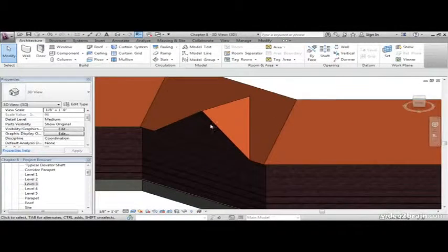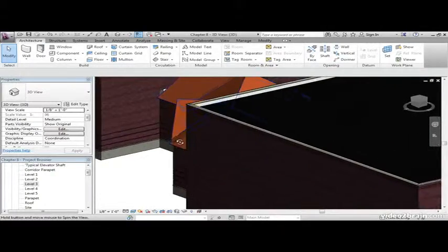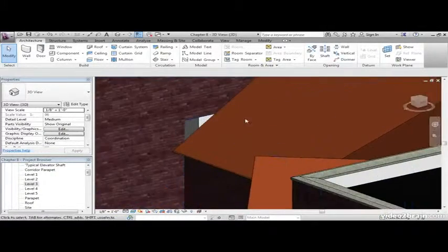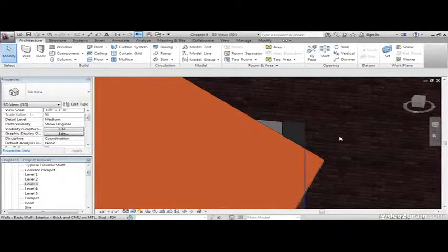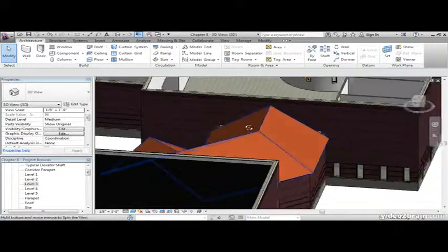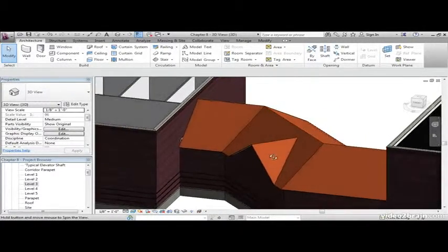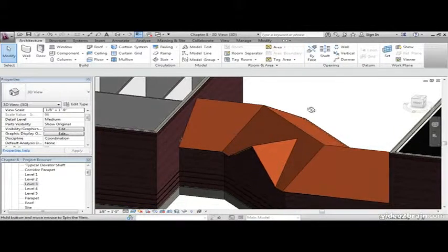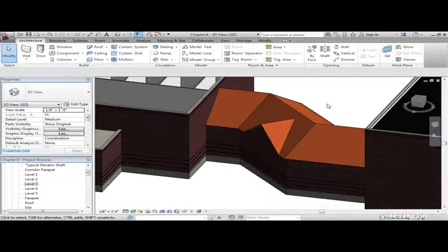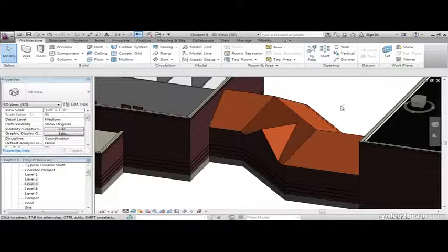How did Revit know to attach the wall to it? We told it to attach the wall before. This wall is attached to the roof. One thing to look at, however, are these horrible gaps in the wall. Well, I always maintain I'm all about precision, and I had you leave some big holes in the wall. I'm not going to lie, I kind of did it on purpose, just to bring up a point. This roof is appended to level 3. We also have a corridor parapet level that we didn't put the roof on, that we should have put the roof on. What I'd like you to do is hold the Control key